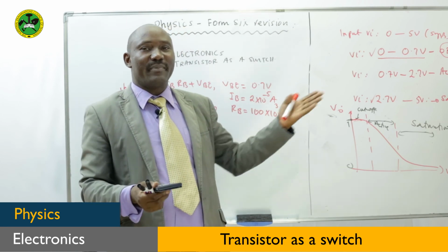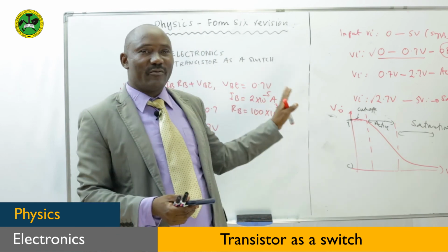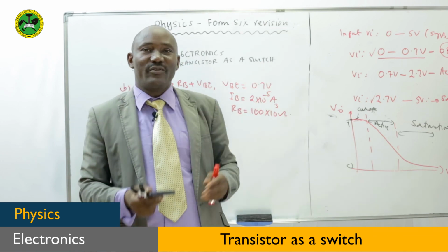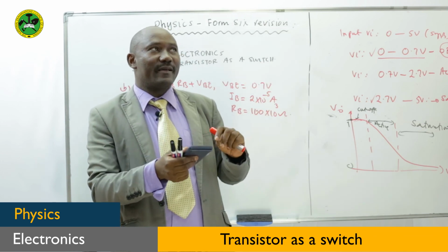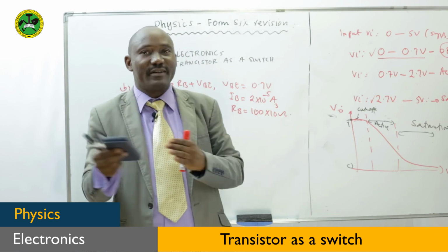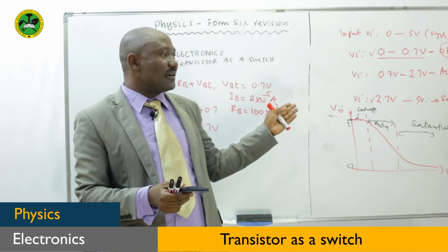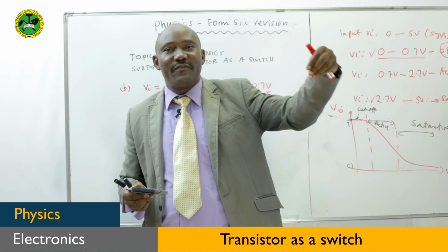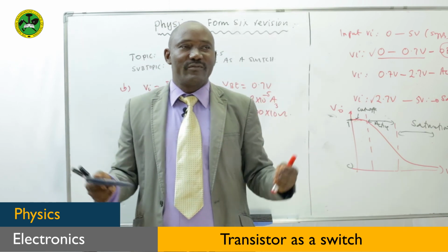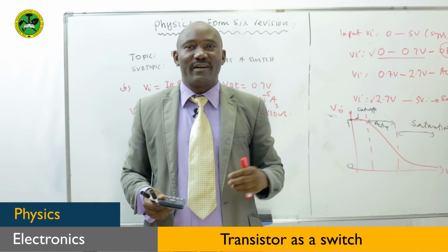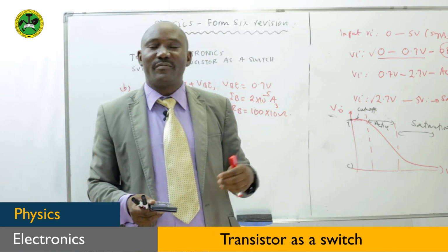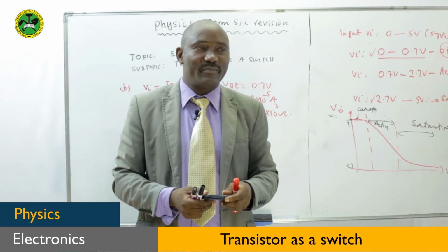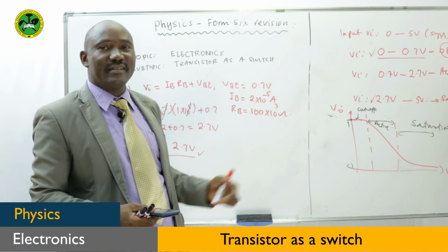This is through the capacitor and the resistor, and we remember we have different types of multivibrators. We did this in your class, and we mentioned some areas where you can use that. When you have two transistors whose saturation points differ slightly, we can connect them such that the output of one transistor feeds the input of another transistor. This is what forms a multivibrator, and we mentioned the types: we have mono, bi, and astable multivibrators. These are different types of multivibrators, which show how a transistor can be used as a switch in various ways.